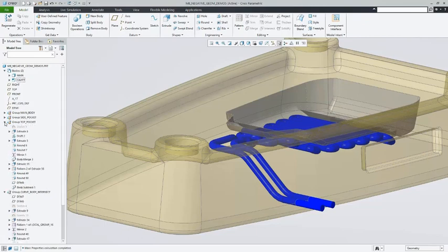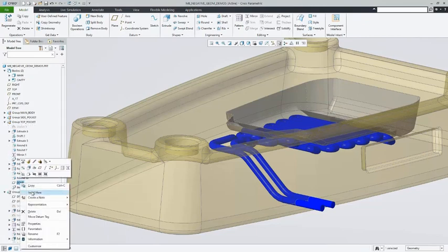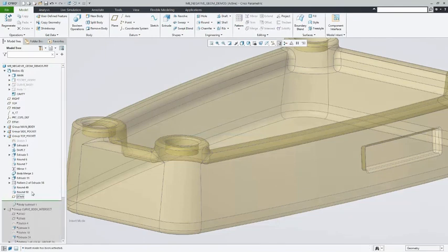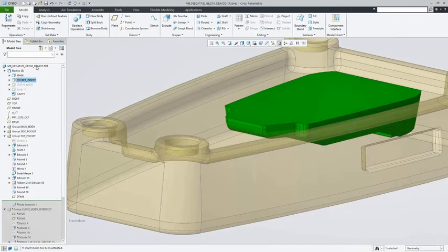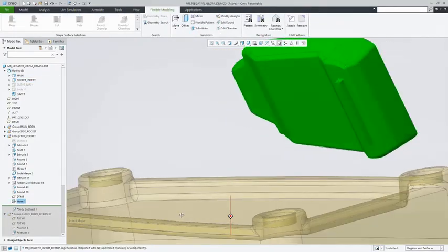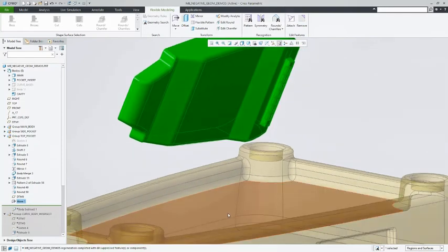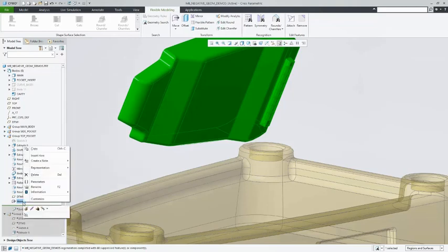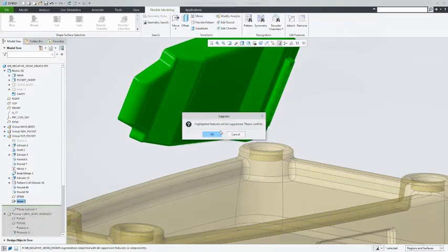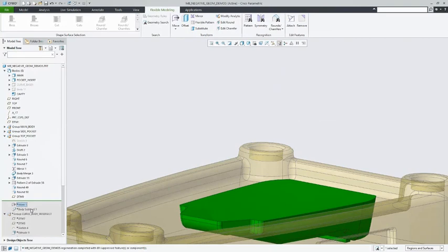Beyond the blue cavity bodies, this design made two additional uses of the multibody concept. First, the green body is used to create the pocket cutout that another part will slide into. This body could be created within the same part, or for example be brought in from an external part, then be positioned with various methods, and then be subtracted from the main design part to create the pocket.